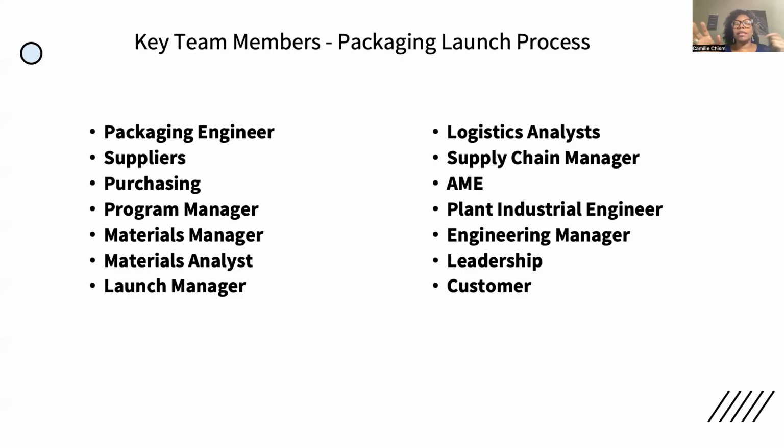But maybe they have 5 different operations there. Now, the person's taking a minute and a half, but the person at the next operation is sitting there waiting because they only have maybe 45 seconds worth of processes to do. So maybe there's some work that this operator, who is a little overtaxed, can push over to the next process. But that also impacts the packaging, because now the packaging is going to be staged in a different area.